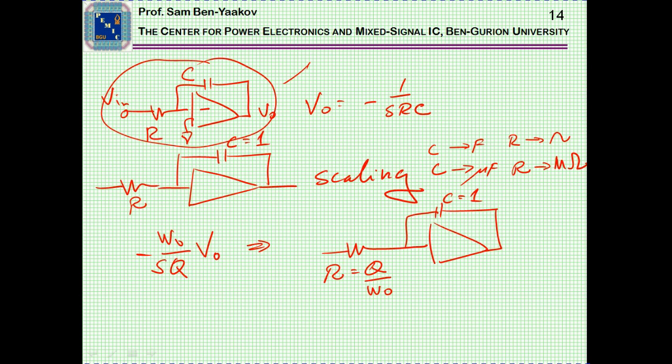And the basic integrator will have this transfer function. Now the values of the resistor and capacitor depend on the gain or the transfer function that we need, and also we have here a degree of freedom. We can sort of scale it in ohms, mega ohms, and microfarad, so that the product, which is shown here, will be the value that we actually would like to realize.